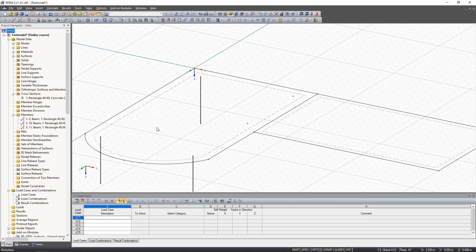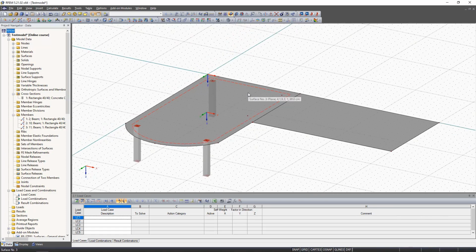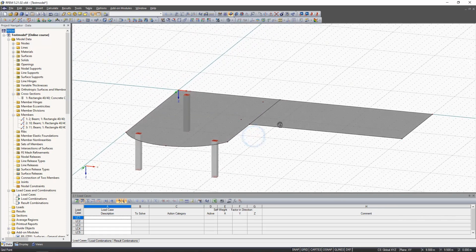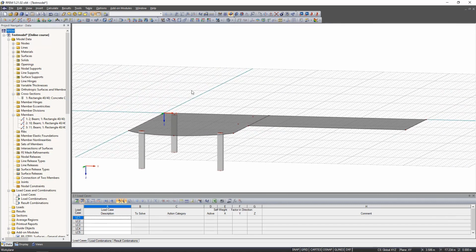Now we want to copy the complete left slab including columns in the right part of the building. For this, we can use the classic move, copy symbol or the mirror. For this, we first select the objects that are to be mirrored. When we drag a selection window from left to right, we select all objects that are completely in the selection window. However, if we drag the selection from right to left, all objects that even touch the window are selected.